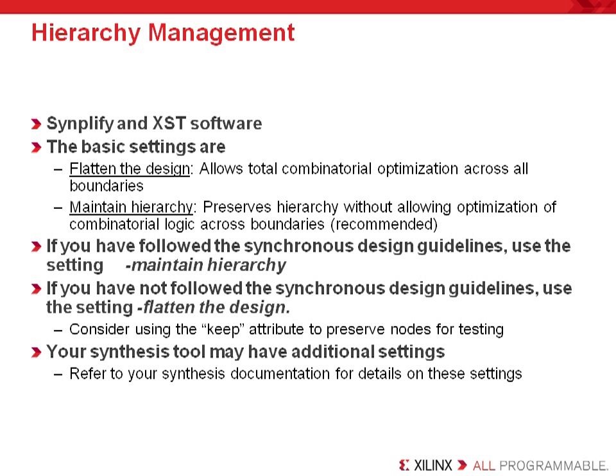Xilinx recommends that hierarchical optimization. Now that is a standard synthesis option that allows users to optimize combinatorial logic across a hierarchical boundary. Now we recommend that this hierarchical optimization be turned off. This is because synthesis tools will change node names and change the logic optimization on nodes that users will often want to simulate, probe, debug, or analyze in some way. Allowing this optimization will sometimes make debugging nodes on a hierarchical boundary much more difficult.